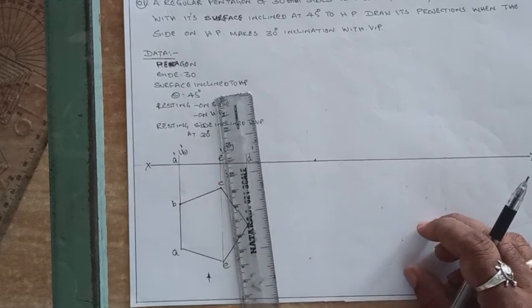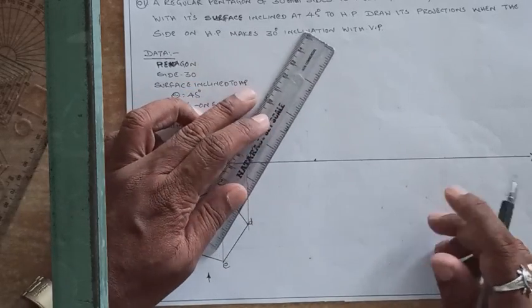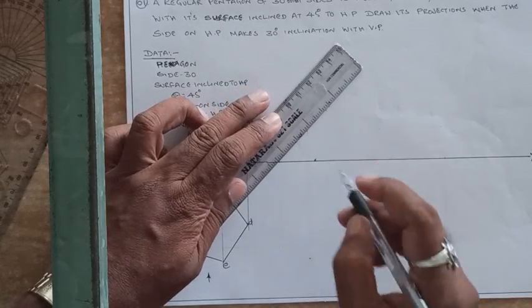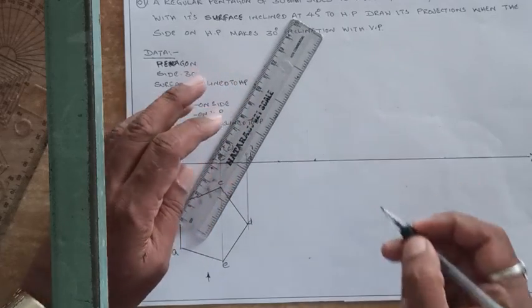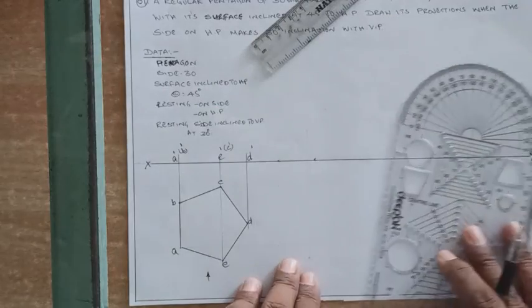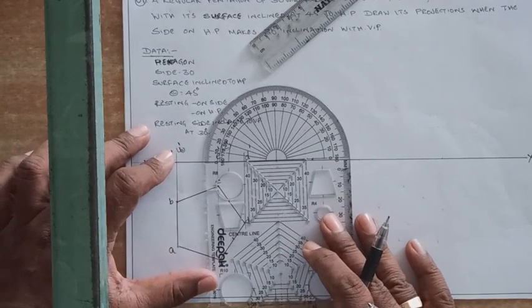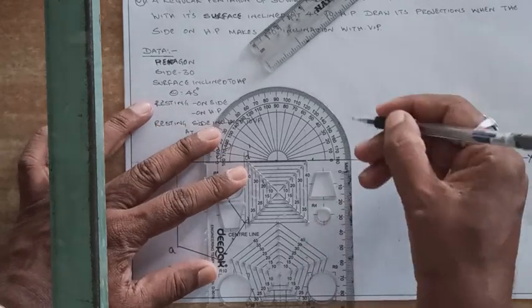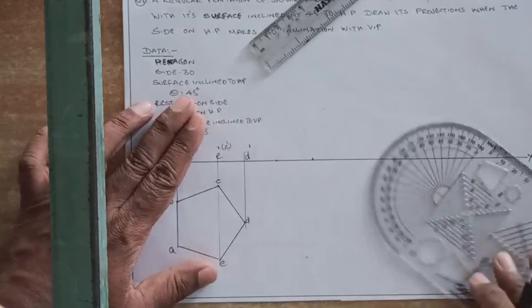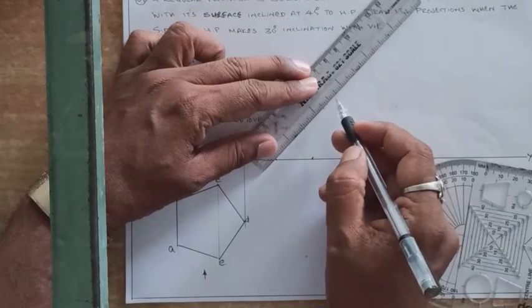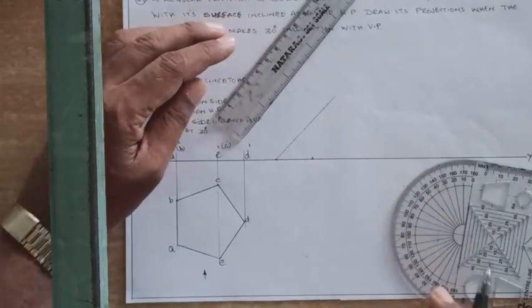Then by seeing the side or corner condition, it was given side, so you have drawn it. Now at one point, mark the point, and the surface is inclined at 45 degrees. So take that point as reference point. That point should be minimum 15 to 20 mm from the figure. Maintain a 15 to 20 mm gap between the figures. So mark the 45 degrees line, then draw the line, thin line first.